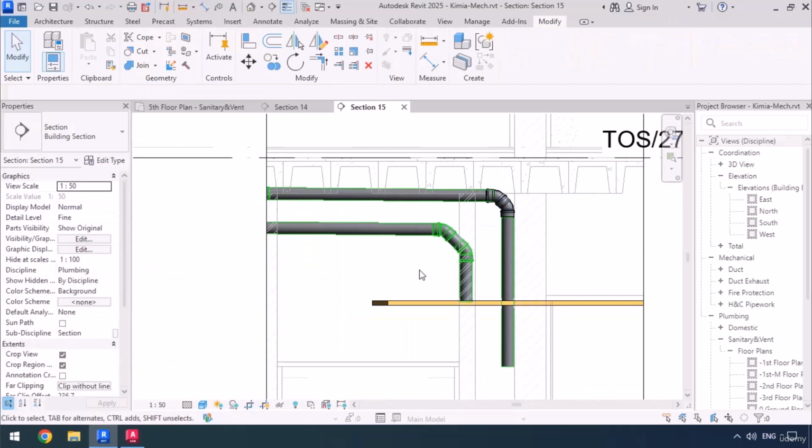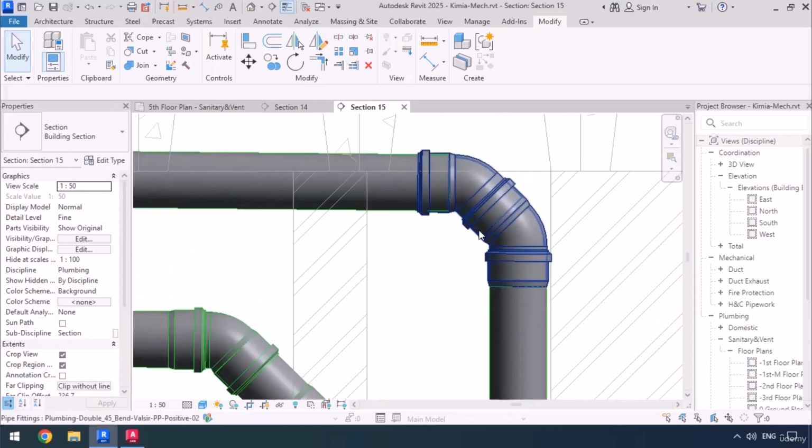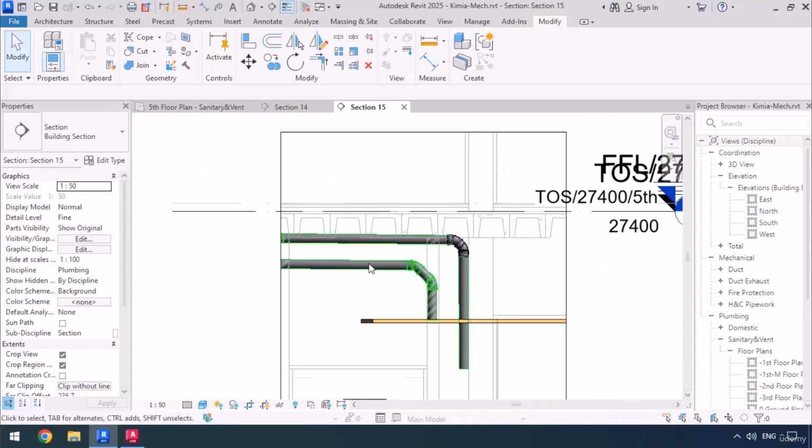So these are the two ways that you could use when drawing your risers, but first you need to know what you are trying to draw and which items you prefer to have in your schedules. When it comes to creating schedules, you should always pay attention to this. For instance, if we see that it says one instance of this family, we should know that it means there are two elbows. We're going to talk all about that in the schedule part.